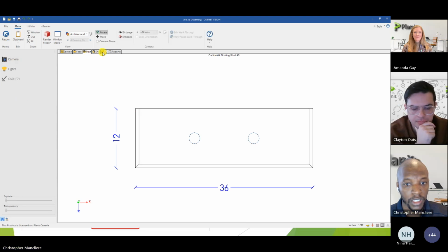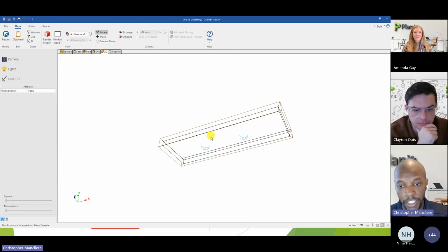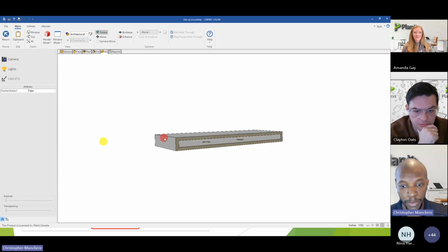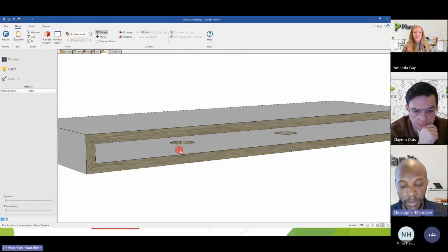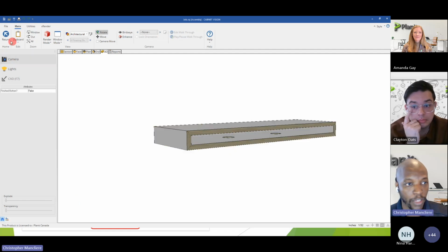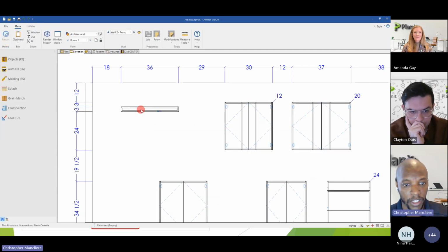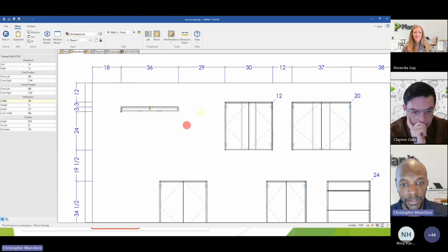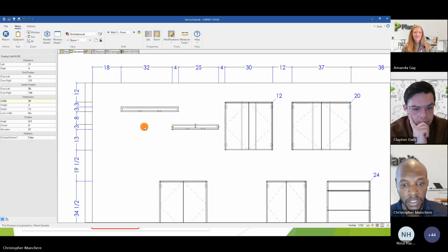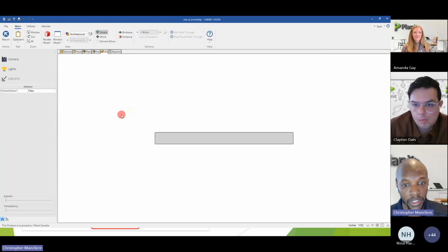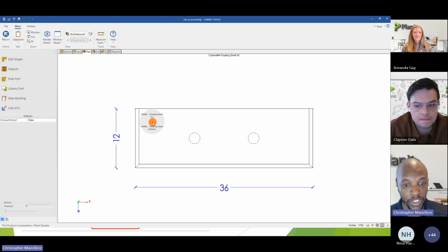Now with my cam editor, what I did, I added my own custom operation, where I also added some intelligence to the operation as well. So now what's happening is if I just copy the same floating shelf and resize it, this will always be spacing out those, maybe a little bit lower, automatically. So this is part also of the shaping tool. So this is adding operation, modifying operation using the CAM editor.